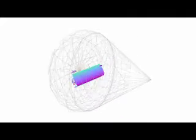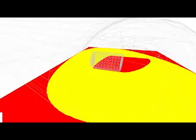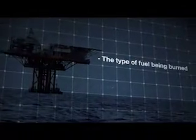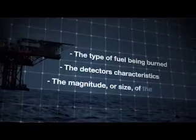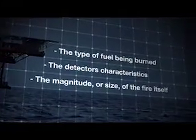Calculating the coverage relies on sophisticated computer algorithms. The 3D model is used in these algorithms to analyze the impact of obstructions on the line of sight of detectors and to evaluate the relative locations of detectors and potential leak sources. For optical flame detection, the ability of a detector to detect a fire is impacted by the type of fuel being burned, the detector's characteristics, and the magnitude or size of the fire itself.